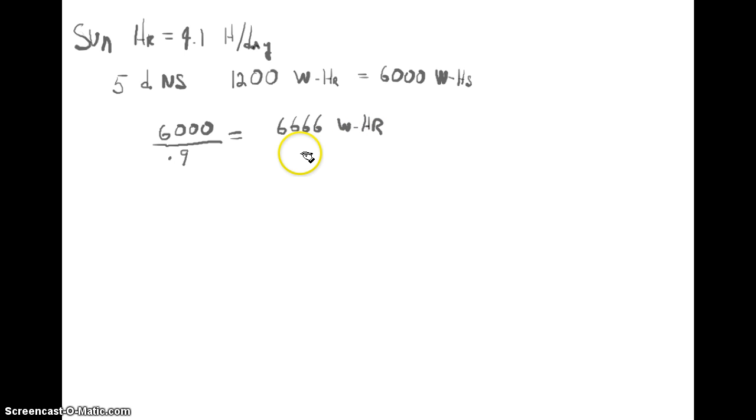Now, as engineers, you have to decide what's reasonable to recharge that. We just can't have a panel stuff back all this in one day, but we're going to have to save up a little every day, a little rainy day deal to stuff it back. So we've got to decide how many days we want to take to charge it back.